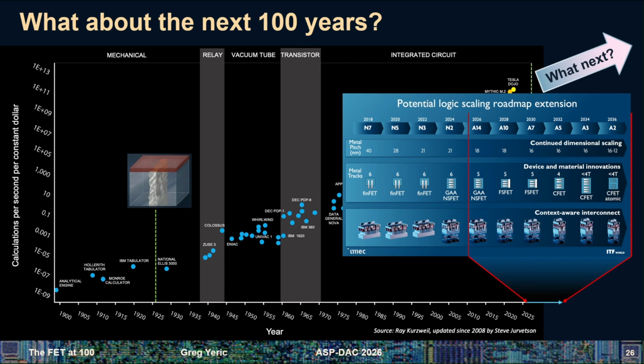Now, we know basically what the next decade holds, where we are producing 2 nanometer silicon. I know TSMC's announced this. The 18A from Intel has been announced. Generally, we've moved from the FinFET era into the gate-all-around era, like the actual picture I showed you at the beginning of the talk. There's a slightly more compact form of the gate-all-around called a fork sheet. This is, I believe, an IMEC actual invention. So it's a kind of a little small step that you get in density.